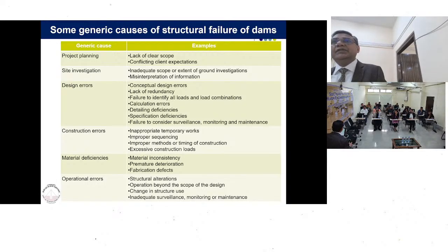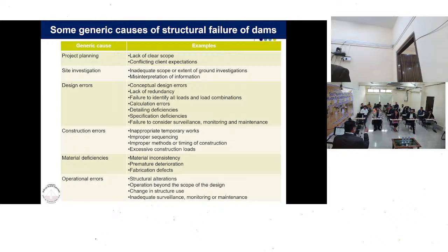And the drilling agency which reached there, the machine they had was not in very good condition. Rather, the drilling head itself was not secure to the machine. So when they started drilling, the drilling head was moving like this. Once the drilling head is moving like this, when you go below, it is going to break the rock cores. So finally you get a core box which has a lot of fractures.